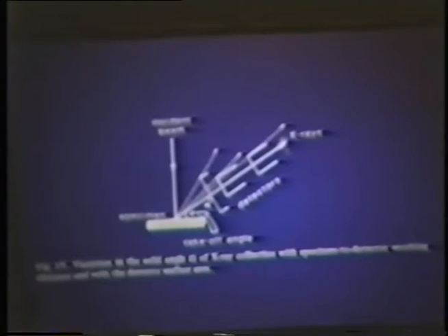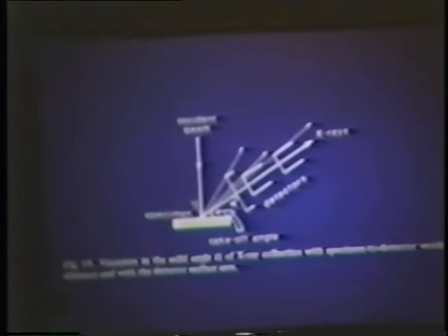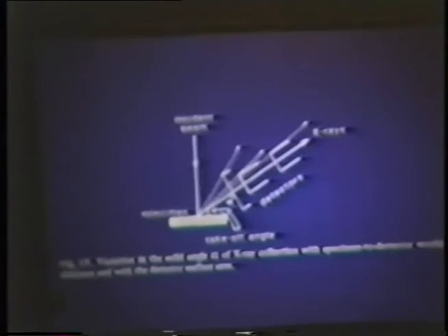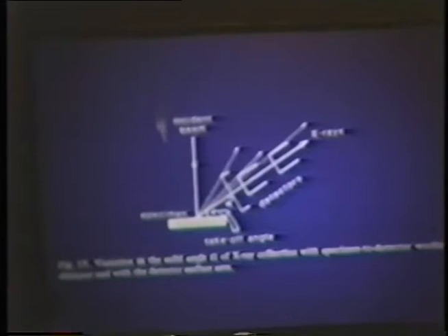We can see here the X-ray detector here and here and here. The closer it gets to the sample, the more of the X-rays it's going to detect. This can be an advantage and a disadvantage. So we need to consider the so-called takeoff angle, a high takeoff angle versus a low takeoff angle here. Make the analogy of looking at this surface with your eye. You will see more of this surface if you're looking directly from above, and you'll see very little of the surface if you're coming in at right angles. A compromise is, in fact, normally about 45 degrees. They vary depending on the instrumentation.